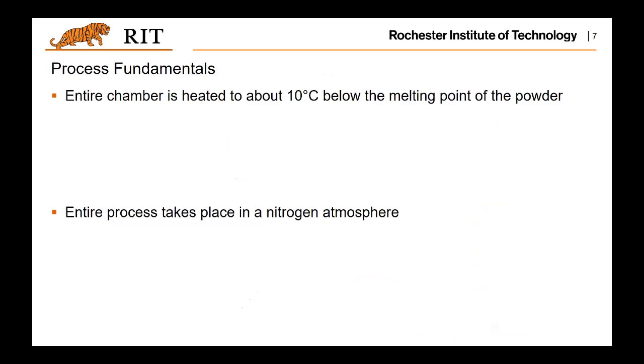Basically, for the SLS process, there will be a chamber, and this chamber will be heated to about 10 degrees Celsius below the melting point of the powder.